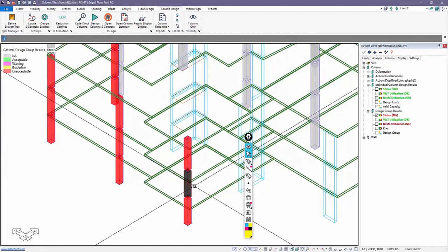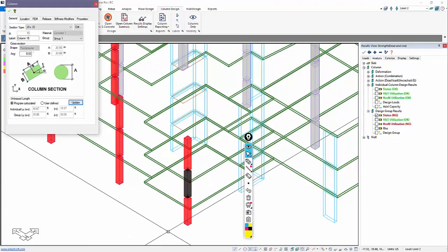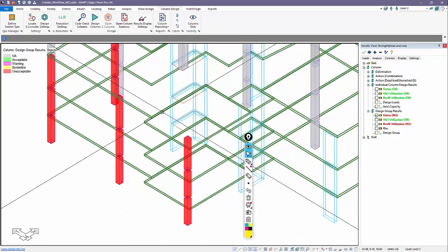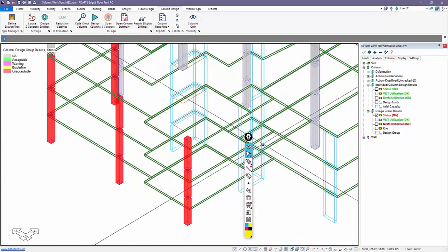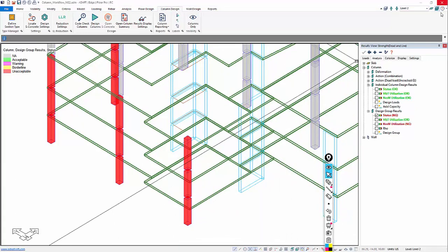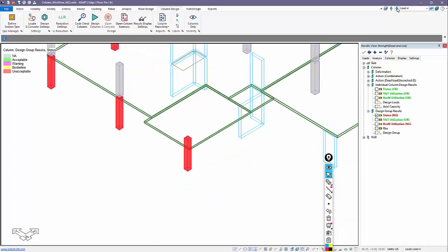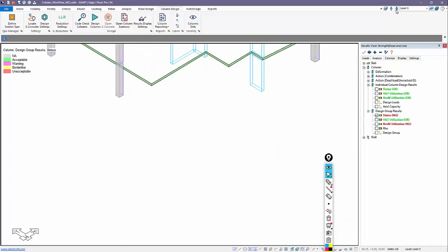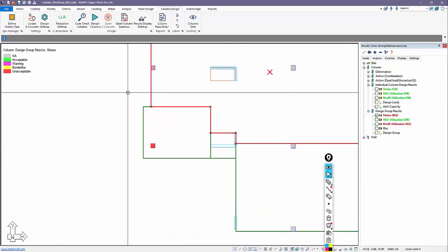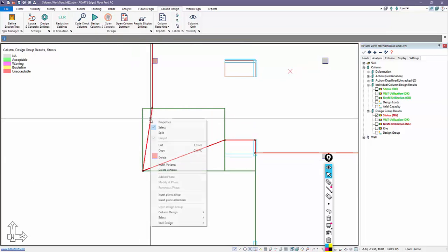And it's based on the way that the slabs are offset and the way that the slabs are adjoined. So the way that we work around this in this case is we have to nest the slabs, and we're going to go ahead and do that. We'll go up to this level here, and rather than modeling this as adjoined, we nest this, and I'll just go ahead and add a couple of points.